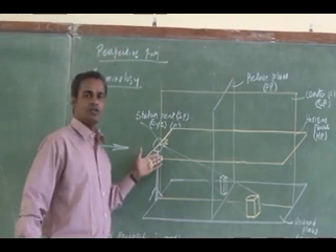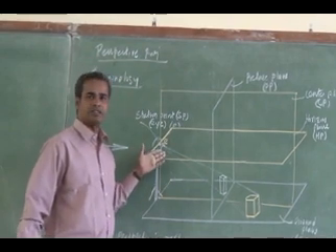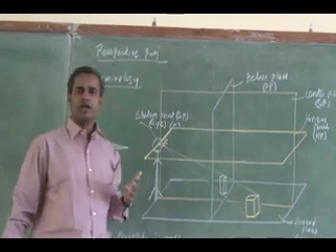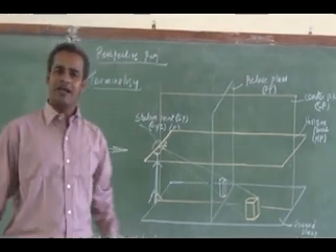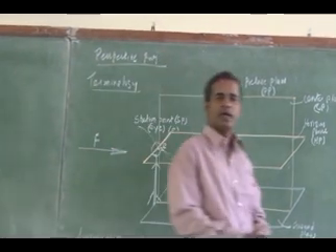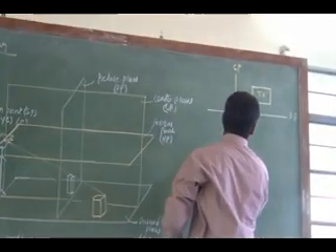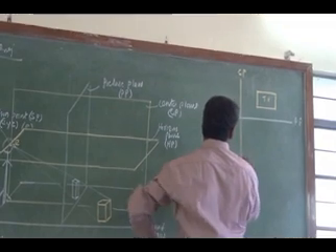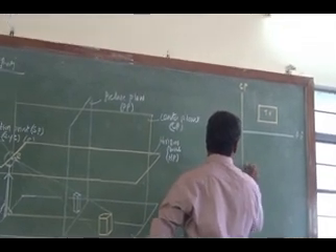Center plane. So you see the center plane, both the yellow planes, the center plane and the horizontal plane, pass through the eye of the observer. So definitely in top view, the station point will fall on my center plane. Somewhere here, some in front distance I will have. So this is my station point E.